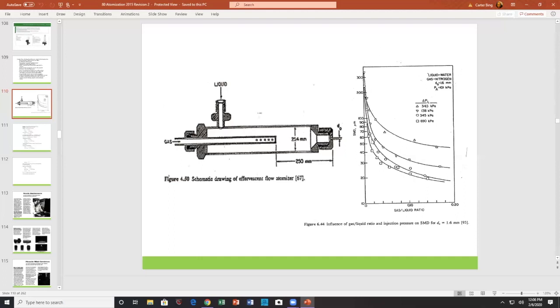When the drops get huge, what do you call huge drops? You call that dripping. So out of this nozzle will come drops. And they don't necessarily go flashing out. They could go down here and collect in a pool. One company I was with, they were burning some really bad stuff, and some of it kept on dripping out of their nozzle. That's because they were running at a very low air to liquid ratio, or gas to liquid ratio. So I have a dripping regime up here. Not good for atomization, bad performance.